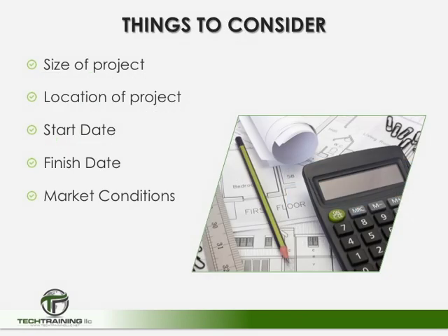Now, also needed, even in a conceptual estimate, are other such items as size of the project, location of the project, start date, finish date, and current or expected market conditions at the time that the project is going to take place.